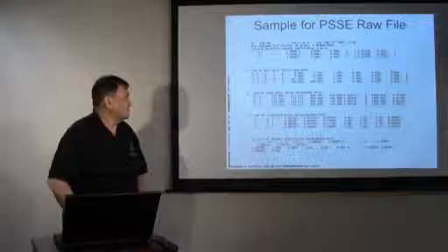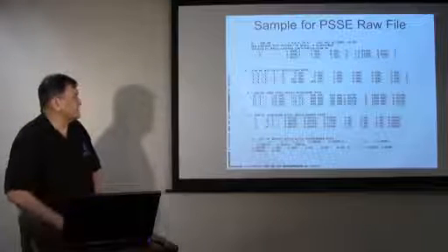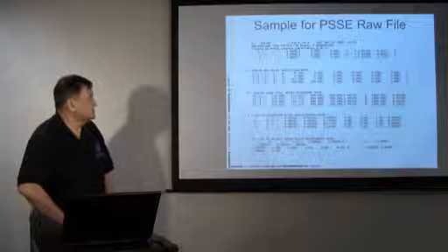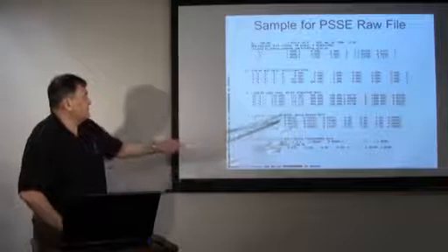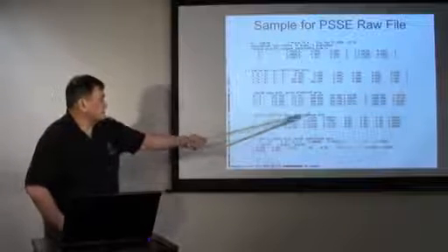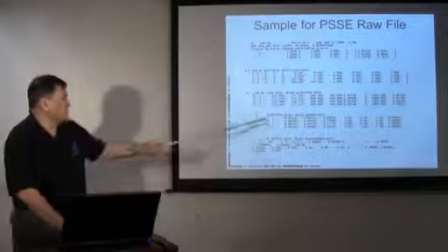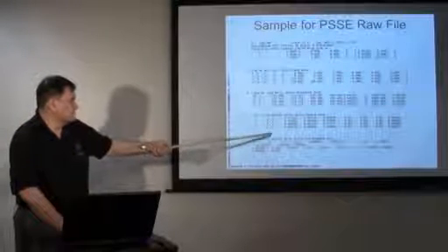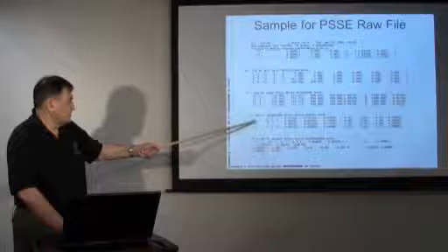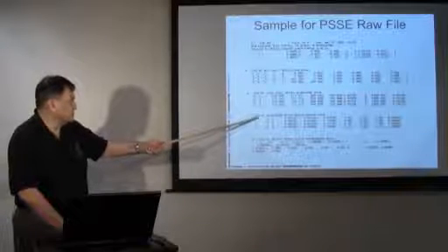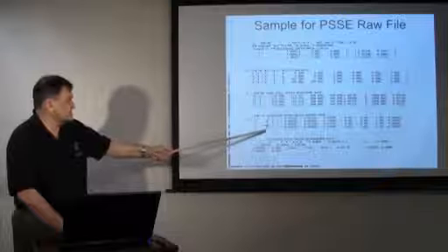And so if I'm somewhat familiar with this, I can see, and again, you had to know these fields, we've got here the branch data. This will be the resistance, the reactance, and the charging susceptance. And here it is, we have the from and the to bus. Those two numbers, that'll be the from bus, the to bus.